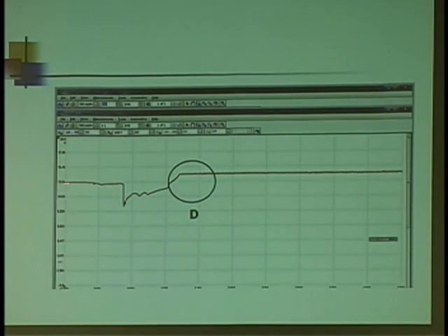So I've got open circuit voltage. I use 12.4 as the threshold. What about you guys? If it's below 12.4, I'm going to charge the battery for a while before I go any further with it. But I know what that reading is because I started right off the bat with it. I can see roughly what the system draw is. I can see what the fully, truly loaded voltage is. I can see what the charging voltage is. And the neat thing is, I didn't stress the alternator or the battery in any way, shape, or form to find out.